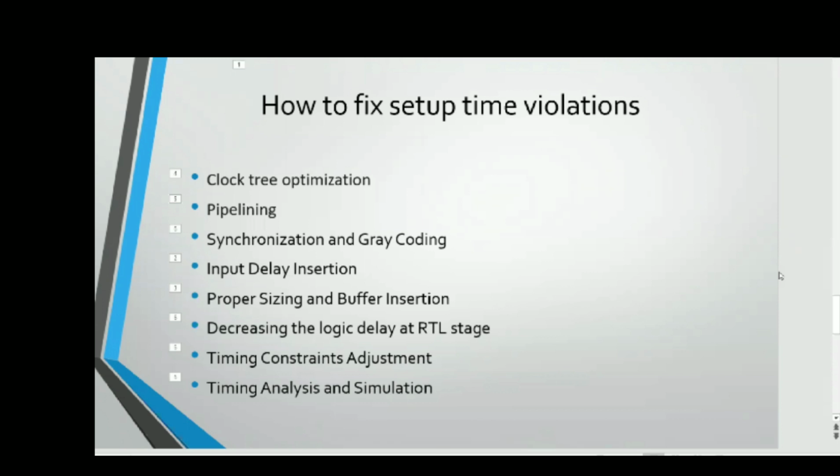Metastability issue. See friends, because of metastability we get setup violation, and also because of setup violation we get the metastable state. Metastable is nothing but a state where your data is not stable at a particular value. You are not going to get the expected output. Suppose you are expecting 0, you may get 1, or you may get some unpredictable value.